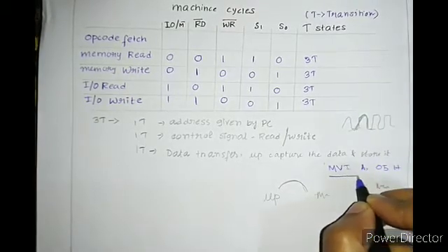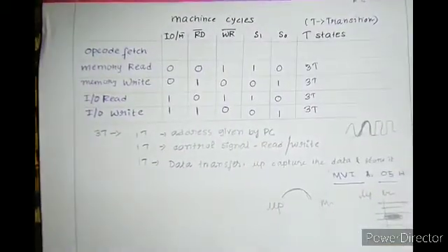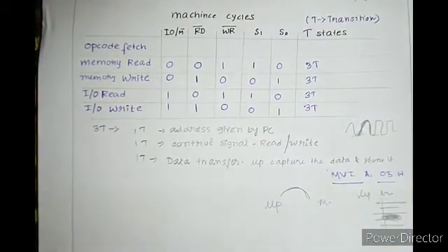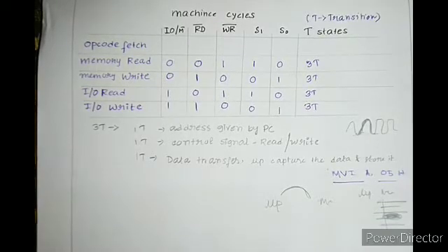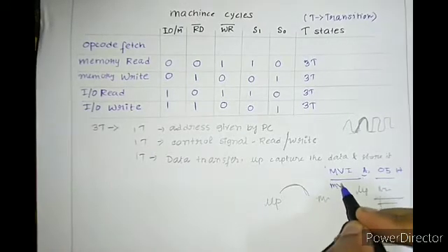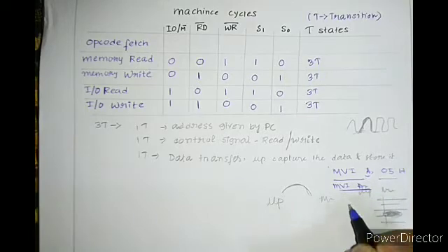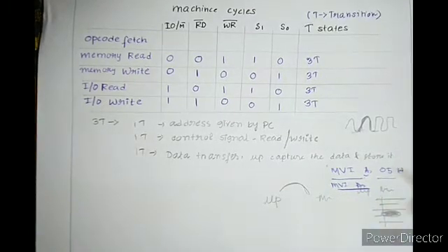This is the opcode, and this is the operand. Now for opcode, there are 74 unique opcodes, I guess. Not for MVI A; the opcode is for MVI any register. There will be a specified opcode, and this data can be whatever, that is not unique, but each opcode has a different combination.